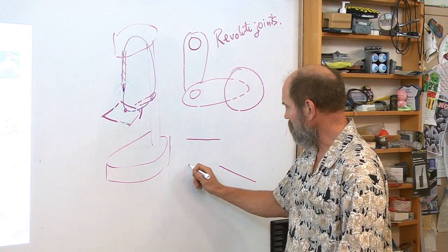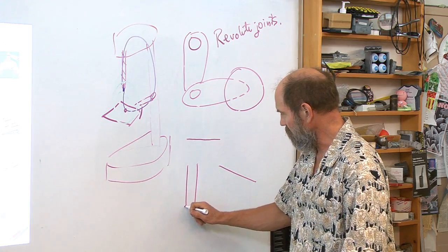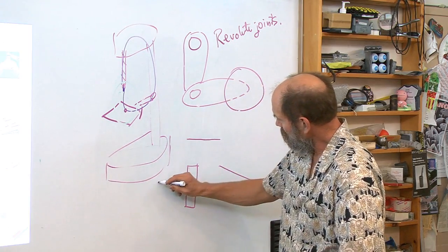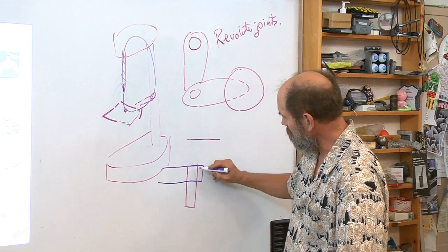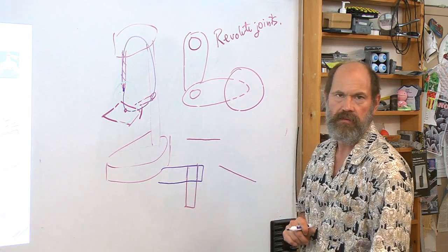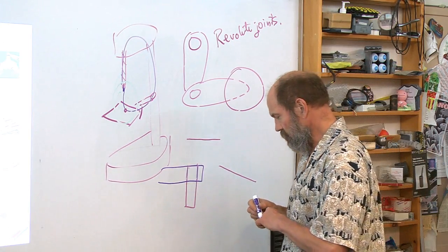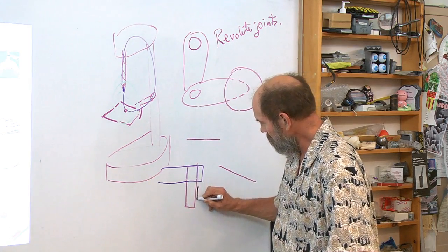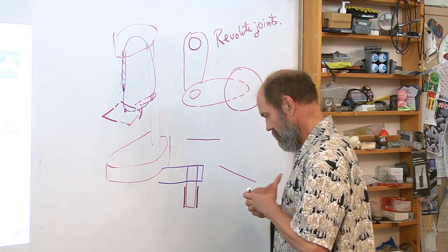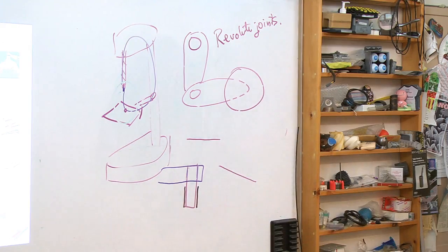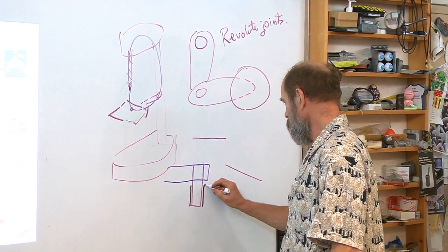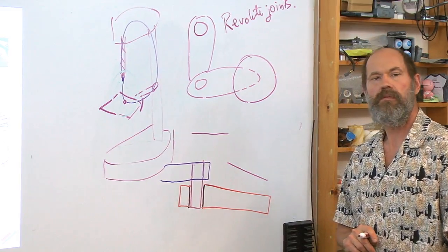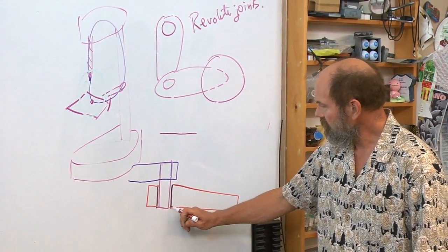Well, let's look a little bit more carefully at a joint. A revolute joint will have an axle or a pivot, and then it'll have the top structure, for example, that is snug with zero clearance and maybe even glued in there. The lower arm, the arm that pivots off of that one, will be some sort of bearing material, and then there will be the arm that comes off of it. Now notice I'm drawing the arm a little bit wacko. And there's some clearance in here.